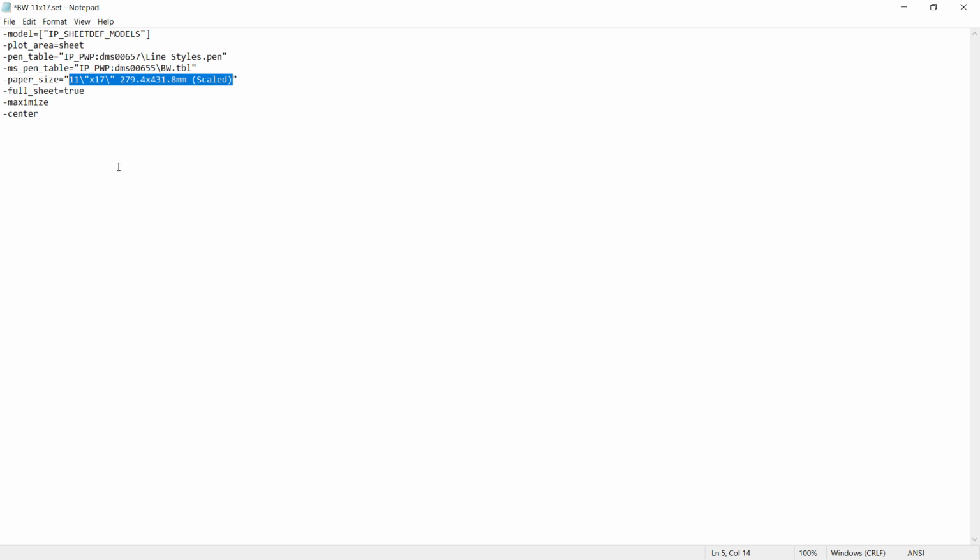But if you do know the name of forms on that plotter, then you can simply replace this text by just typing what you need. For example, I know there is no 11x17 form size available on that Dynamic Composition Server printer, but it does offer me tabloid, which will give me 11x17.